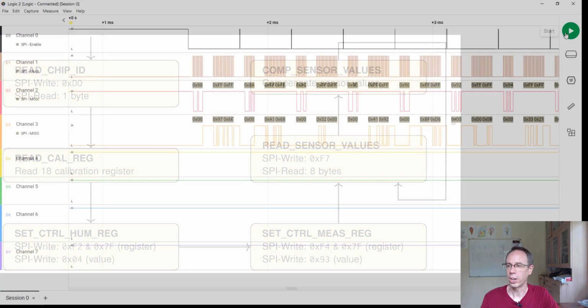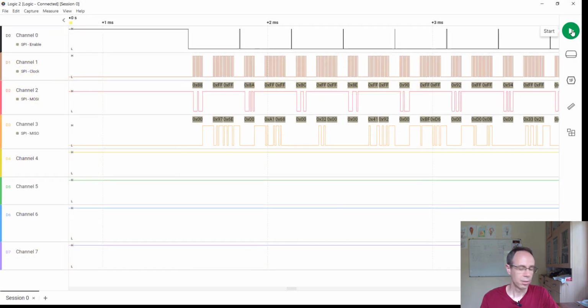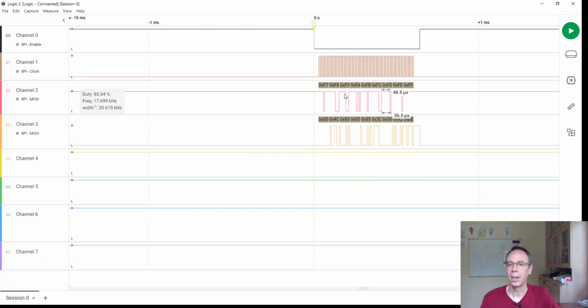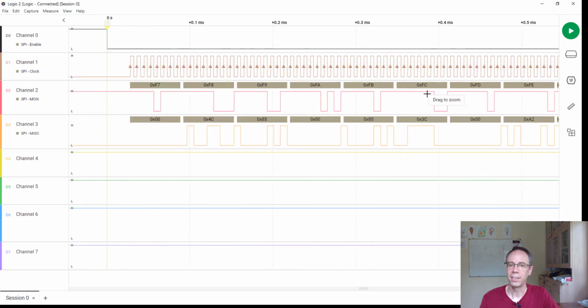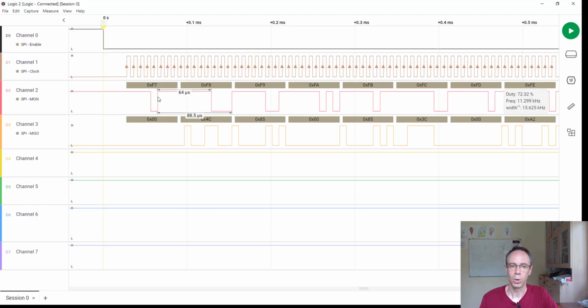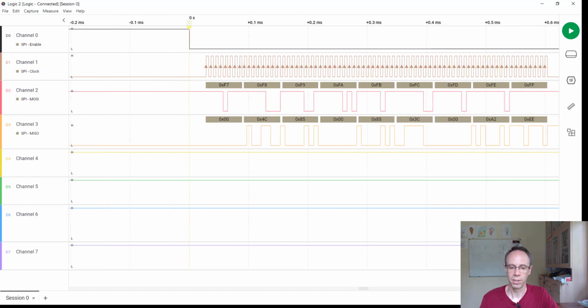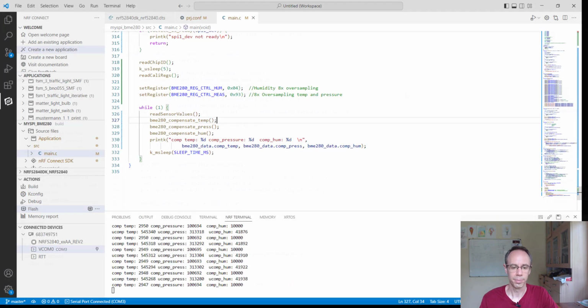And you can also check it here when we are making it now with the logic analyzer. You're seeing here that in this time we're reading out at once, so we are sending and receiving something at the same time. This was the difference when we're making transceive instead of read-write.